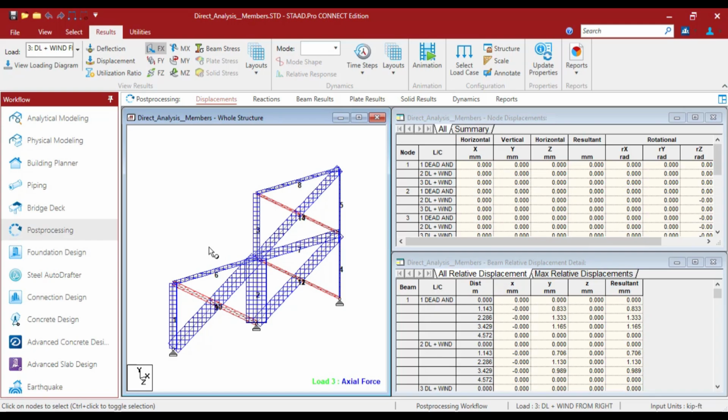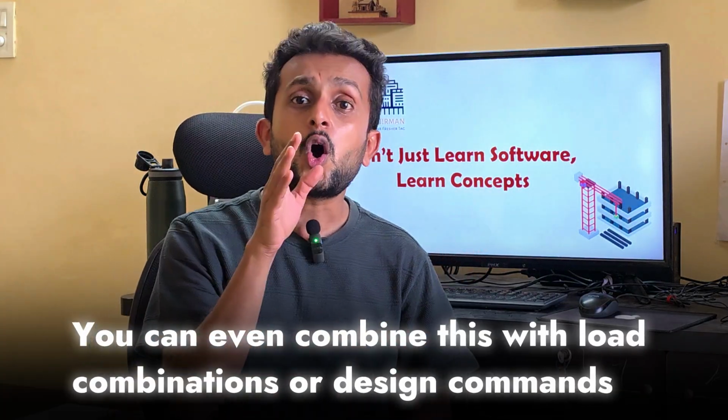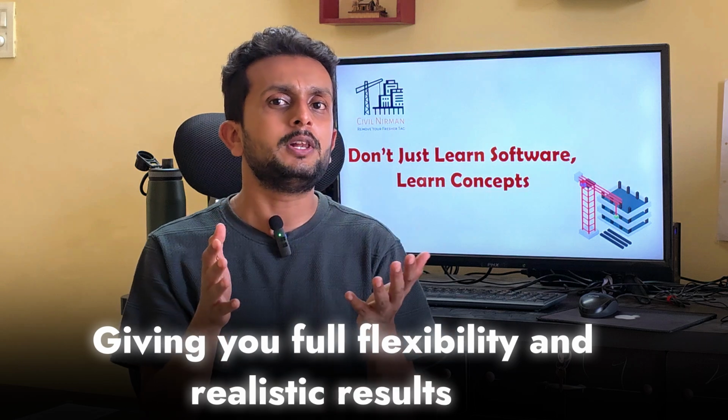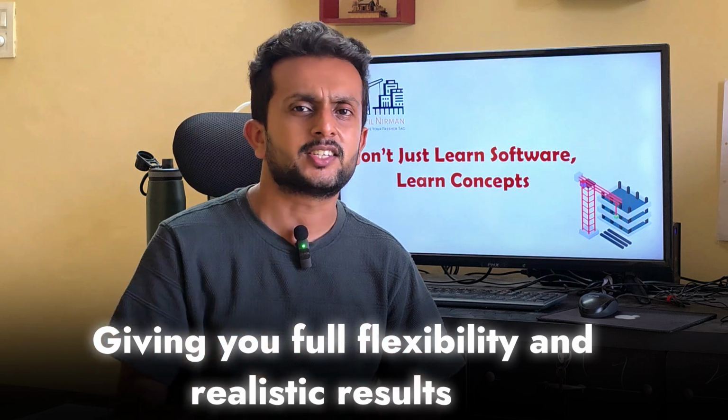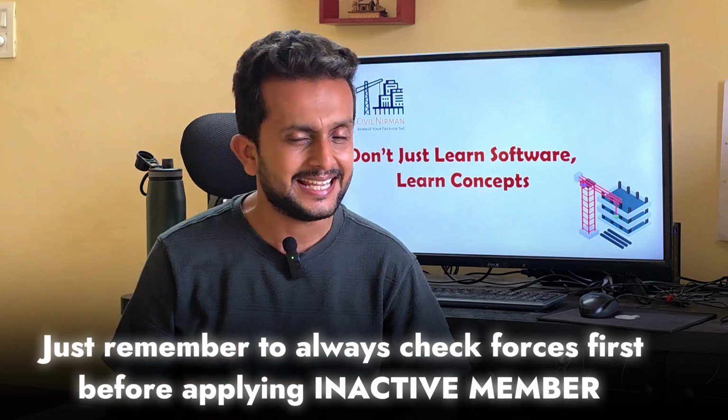Now why does this work? This approach mimics the real world brace behavior without complex non-linear settings or iterations, and you are letting STAAD handle load specific logic while keeping your model clean and correct. You can even combine this with load combinations or design commands, giving you full flexibility and realistic results. Just remember to always check forces first before applying the inactive member.